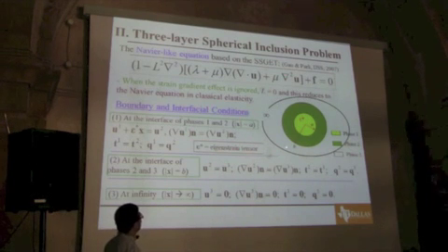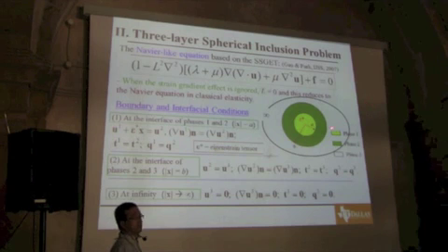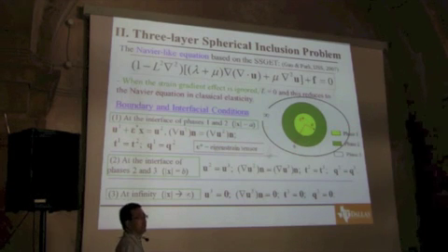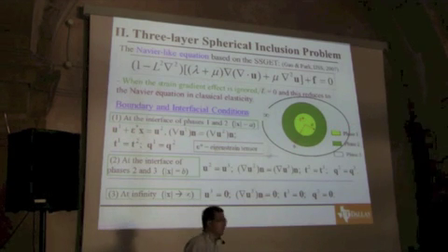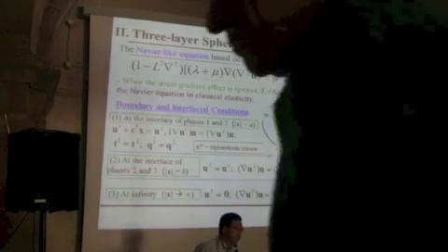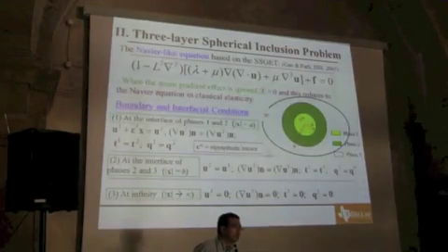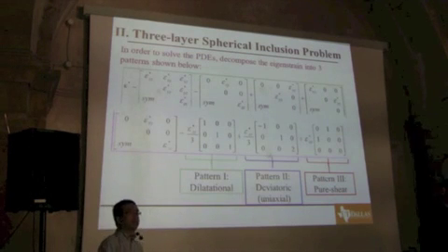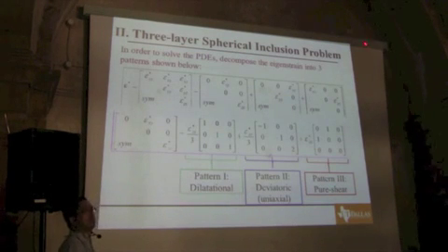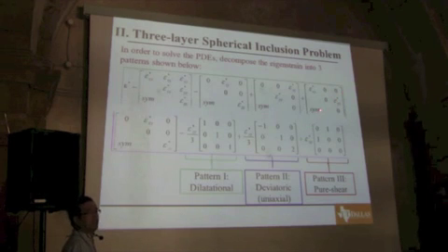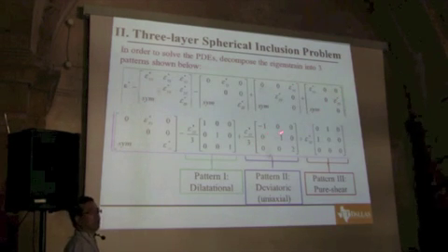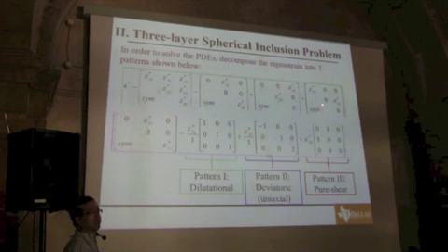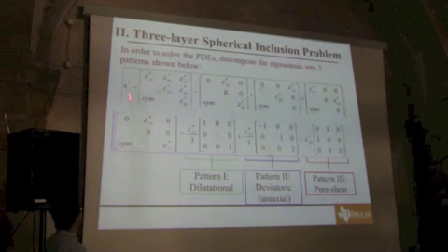But the eigenstrain tensor prescribed here is arbitrary. So we treat it with all 6 independent components being non-zero, with zero ones, of course, being special cases. How can we have this problem solved? It's a little bit tricky. But since everything we are dealing with here is linearly elastic, the most powerful tool to use is the superposition principle. So that's what we did.